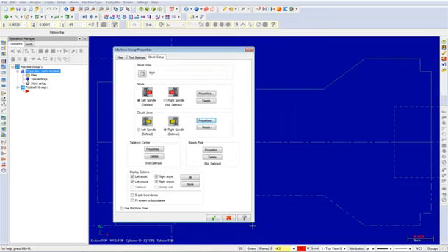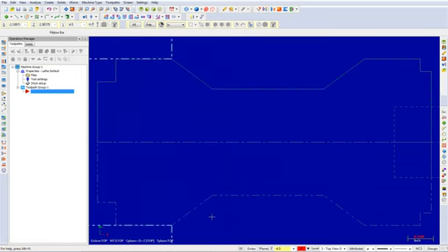From here, enable Fit Screen to Boundaries in the Display Options area. Then select the OK button to exit Machine Group Properties. Select the isometric view from your toolbar and use the Fit icon to see the drawing on your screen.